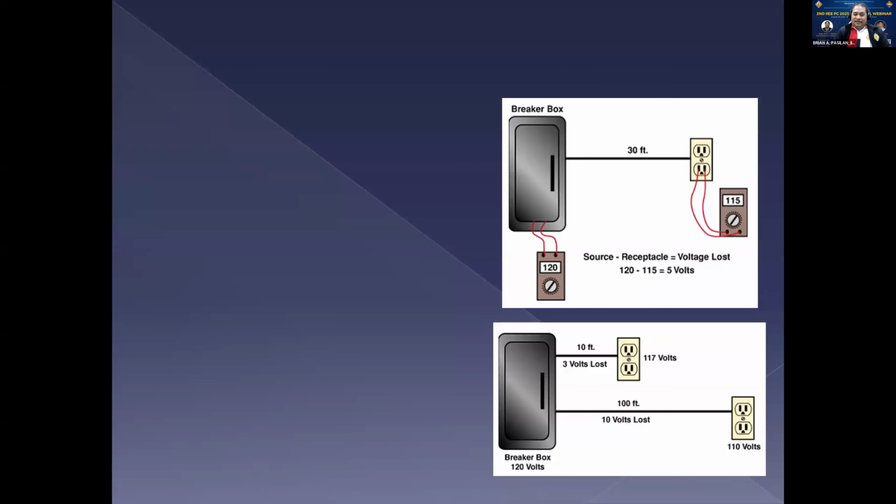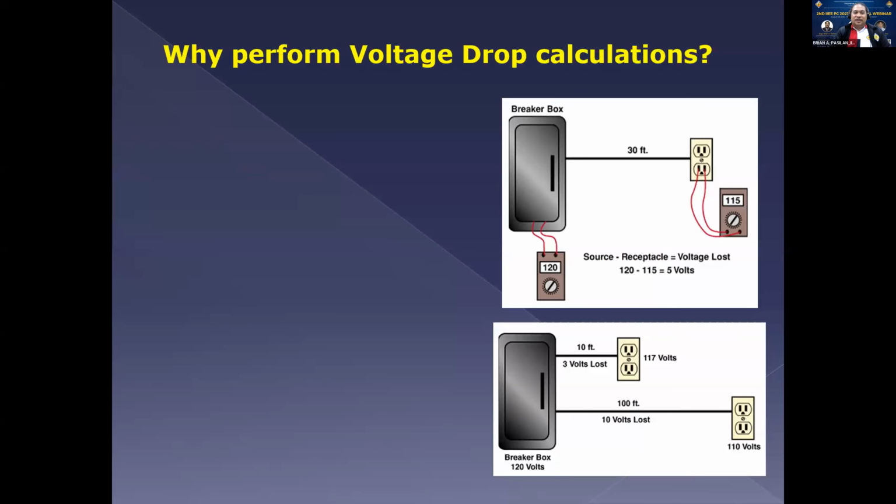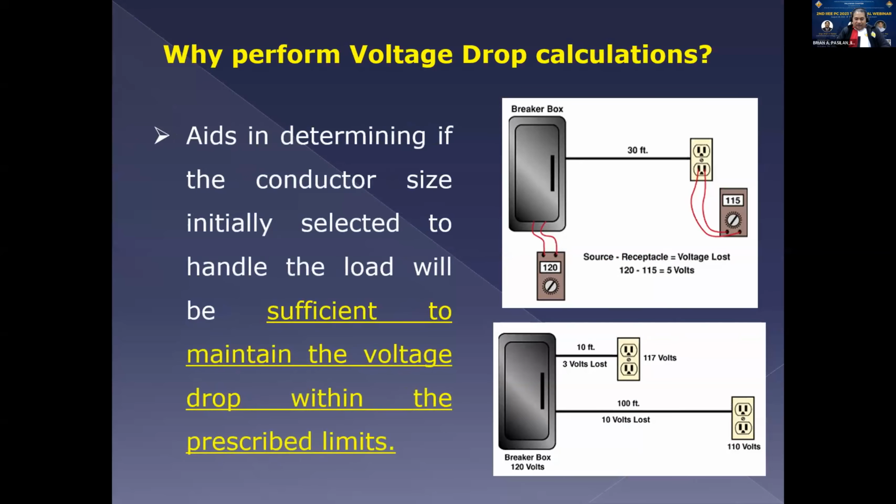Okay. So at least now we know the importance of having a load schedule. Now for voltage drop calculations, no? So ano yung benefits na pag we do evaluation of voltage drops? So it can also aid in determining the conductor size, no? This is the second step, actually, in verifying the conductor size to be specified, no? If sufficient ba yung voltage level at the load end, from one point to the other.